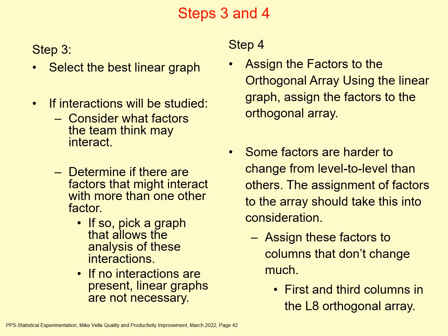In step 4, we're going to assign the factors to the orthogonal array using the linear graph. Assign the factors to the orthogonal array. Now, some factors are harder to change from level to level than others. The setups are longer, or maybe the materials are harder to change over, or it just costs more to change factors from one trial to another. The assignment of these factors to the array should take this into consideration.